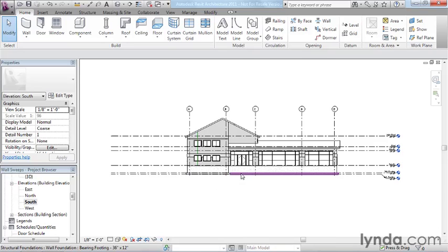To actually carve away a little half-inch reveal to try and represent that, first of all, it's going to print way too bold because you're going to have two thin lines right next to each other, which are going to look like a thick line. So that's not going to look so well. It's going to be tough to control. And it's just going to make your model heavier and make it perform less optimally than it would otherwise.